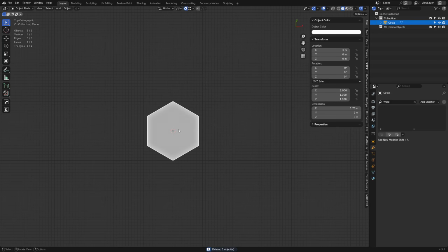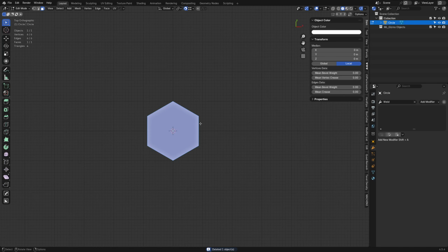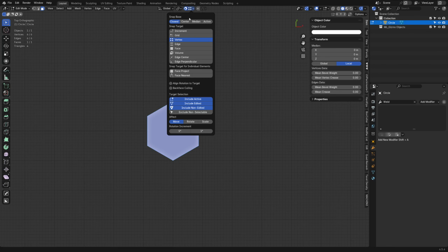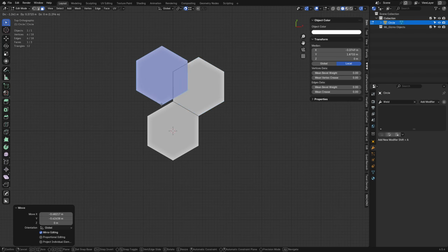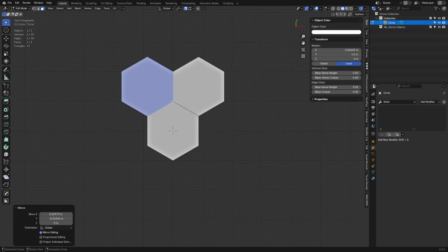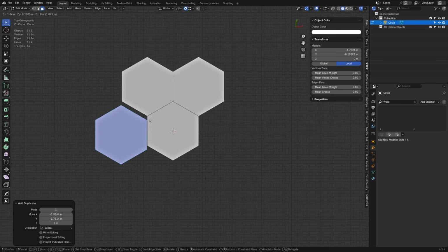The way I've always done this is I would be in edit mode. When you're in edit mode, vertex snapping actually works correctly. So if I Shift D and duplicate, if I go and duplicate it out to that side, it's going to use the closest vertex. I can hit G now. Boom. So move it out, go near the vertex you want. Snap very fast and do this. Okay.